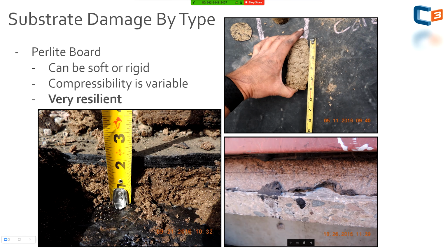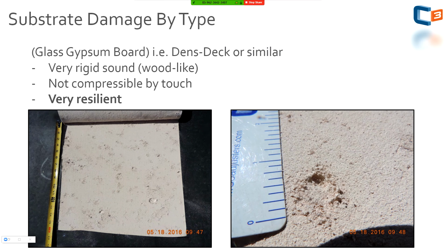In this case, it was an old roof. They used hot asphalt to bond that. But there's going to be waterproofing from that hot asphalt, right? That's sealing in the seams of the concrete. So if you have water infiltration, it might not even make its way inside the structure. In this case, that's exactly what happened. But just to show you how important cutting is, going back to that built-up photo, we'll core right next to the hail impacts in the field as close as we can. In this case, the whole field was saturated, but...